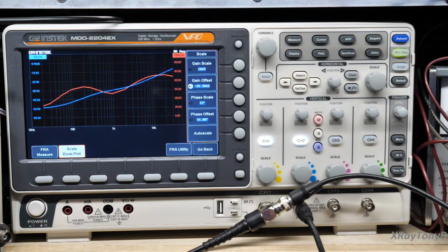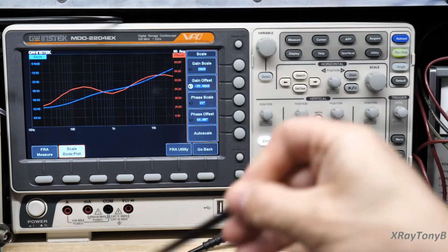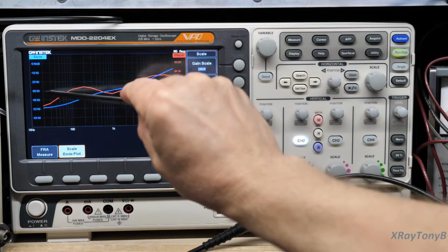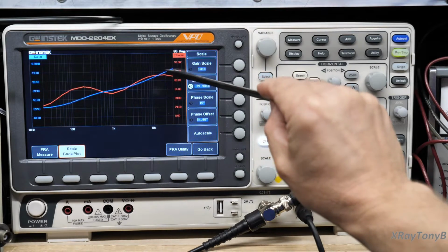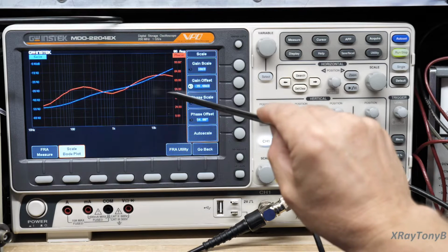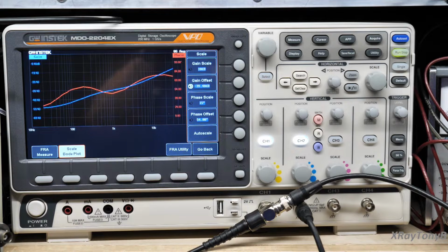Or should I say the inverse of it, because what's going to happen is you're going to have the opposite of this programmed into your phono stage, and it's going to boost this signal back up 20 dB, and it's going to cut this signal at this end down, at this frequency, down 20 dB, and make it back into a flat signal, if that makes sense.